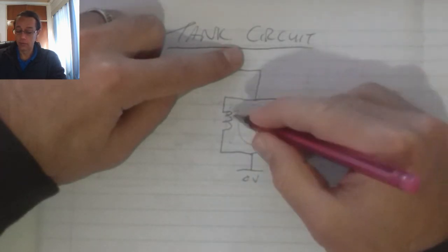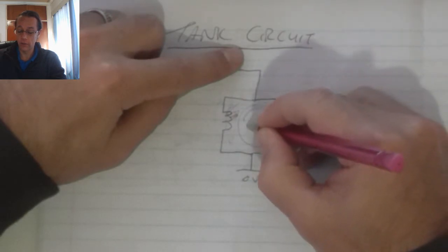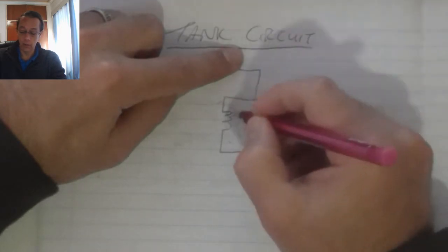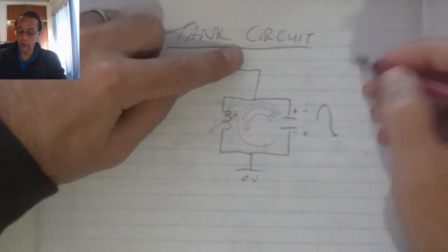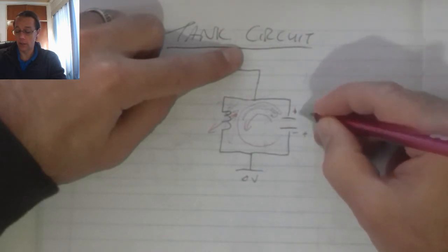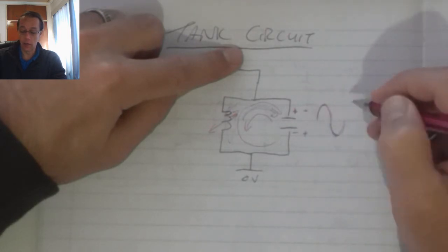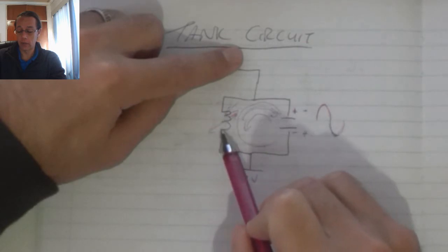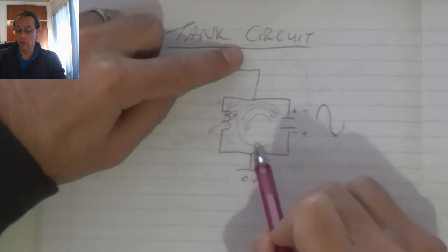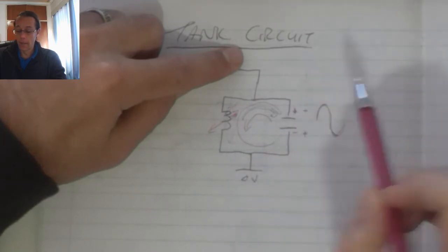Because there is no more potential, this capacitor now has to discharge again, and it does that through the inductor, which in turn creates a new magnetic field in the opposite direction, but in doing so it loses that electrostatic charge, bringing its voltage back to 0. Now when this magnetic field collapses again, the inductor is going to charge the capacitor back in the original direction.